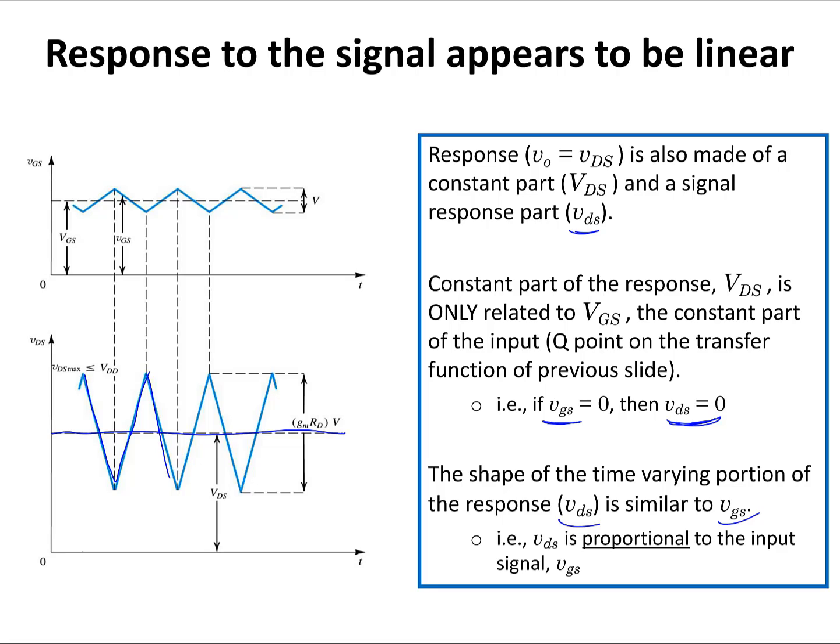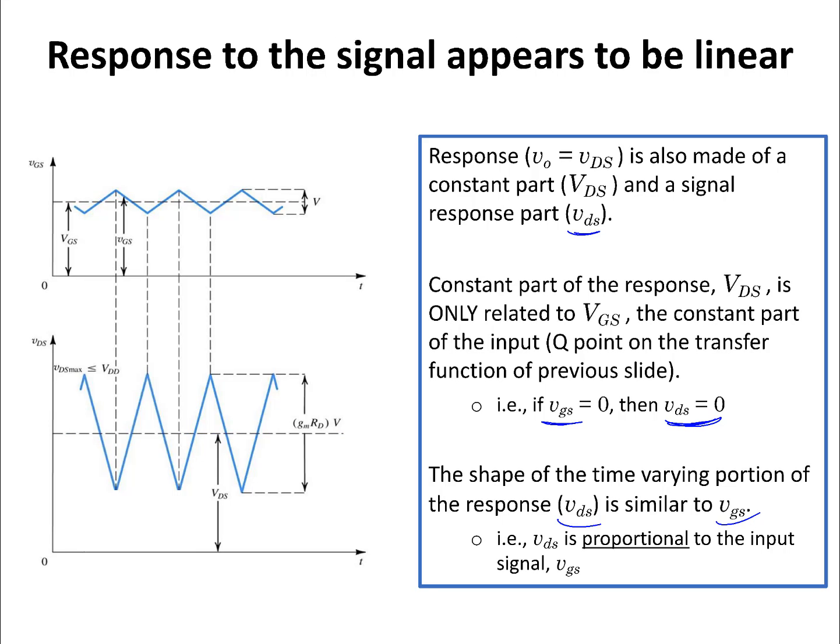In summary, we saw some examples of using MOSFET or BJT devices as linear voltage amplifiers. We saw some simulation results of using these devices to amplify AC signals with small amplitude applied to these devices and getting a similar AC signal, but amplified and inverted, at the output of the device.